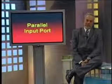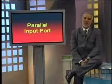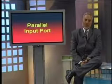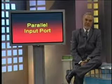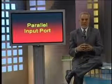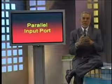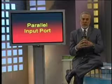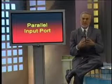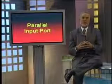The next important thing you notice in the figure is that all the 16 lines are isolated by using tri-state buffers. All these buffers are enabled simultaneously, so the enable lines of all these tri-state buffers are connected together, and the enabling signal would come from the decoder. The decoder utilizes only the low 8-bit address lines from A0 to A7. For this example, A0 and A7 are inverted and the others are in true form.